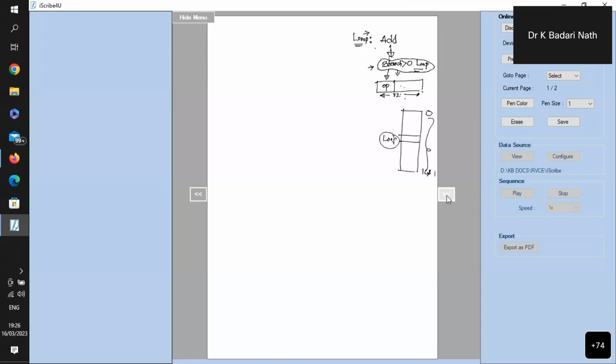But instead of referring to it that way, suppose I refer to this address called loop from a place, say I'm executing at this place now, at this moment. My program is there, an add instruction, and here a branch instruction is available. Now, if I want to find out how far the loop is from this place, then instead of representing the complete loop address inside the instruction, if I just indicate the displacement, how far the label is where I am supposed to branch, it takes very little space in the instruction.